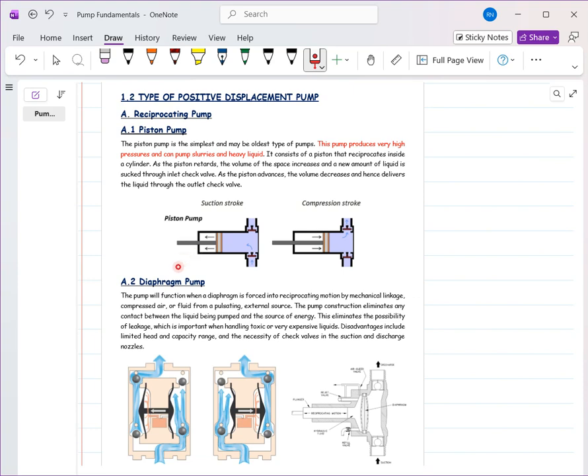As we discussed, it takes a fixed amount of liquid, because it is designed in such a way that for a constant flow, the chamber has 1 liter volume. It sucks in 1 liter and then discharges the 1 liter, right? In 1 minute it makes 50 strokes, so the constant flow rate should be 50 strokes per minute.